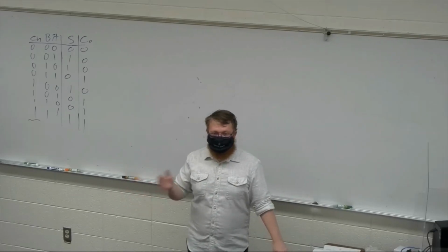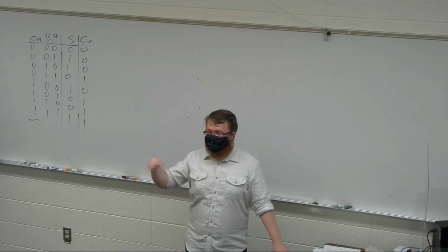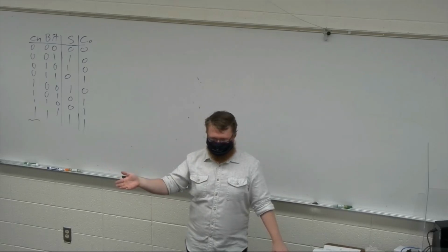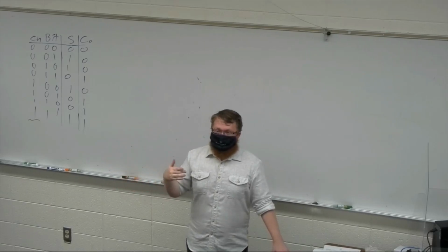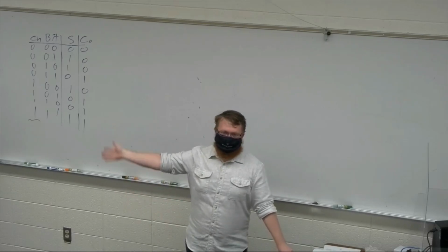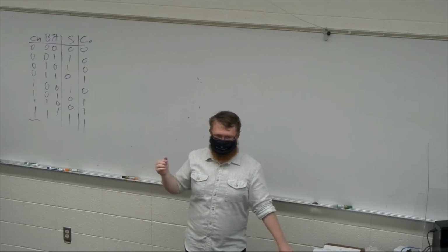The first is if it's just a clock running and it's trying to see if this is 1 on my clock, let's add to the counter. Well, the issue is, I'm going to push it and let go, and no matter how fast I do that, it's still going to be a couple milliseconds, maybe, right? And that clock at 100 megahertz is going to count from 0 to 180 or whatever it ends up being, right? Just like, ding, ding, ding, ding, ding, and we're like, oh, well, I didn't do very good at that.